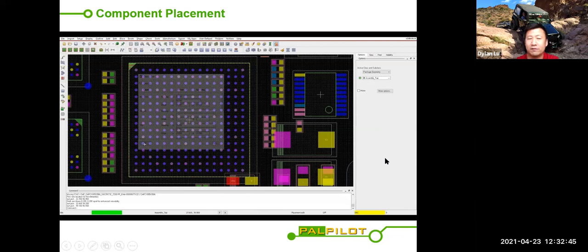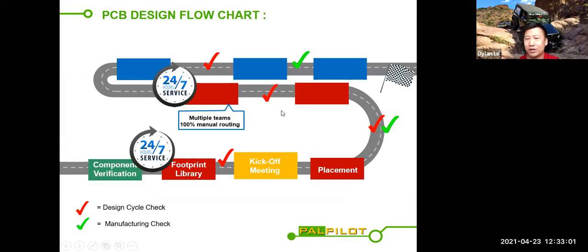So placement is very important for all the supporting components. Depending on how far you want them to be or how far they have to be, you have to place them strategically. And that will help you go to the next step, which is going to be your routing. Because after you place all the buildings, I use the analogy for routing as point-to-point connections. So you can probably treat it as building the roads in the city.